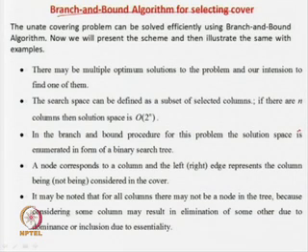Okay. So, some of the techniques we will see, but the basic core idea is that the whole problem can be represented in terms of a tree. Okay, and there are multiple optimum solutions, and our intention is just to find one of them. So, you can find 3 or 4 solutions, that is 3 or 4 subsets of the prime implicants taken, and all correspond to say 3 prime implicants, then you have 3 solutions of equal value. But then again you can dig into finding out the number of literals in each of the prime implicants, that can give you again a finer value.